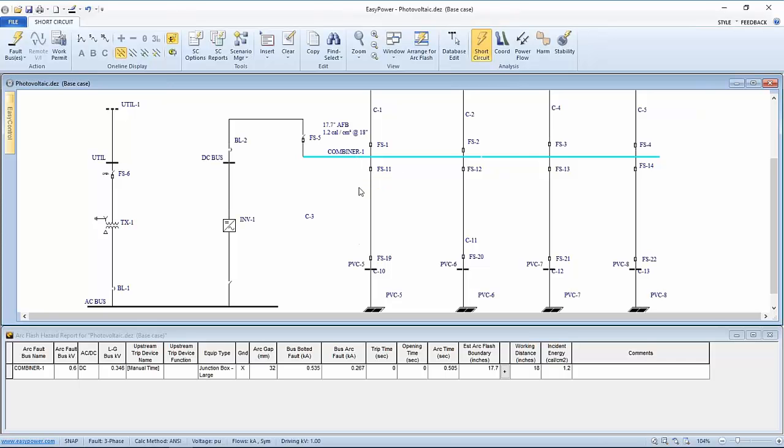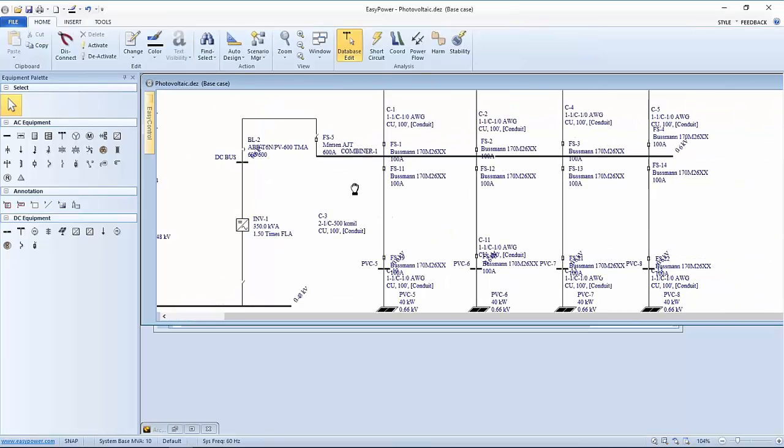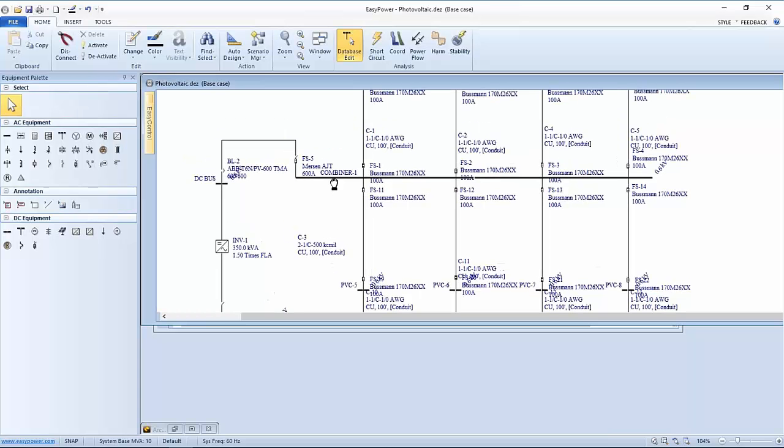I don't recommend that anyone be cavalier in these considerations, but when we're talking about a maximum of 200 amps and a voltage of, I think it was 600 volts, that is dangerous, but it's not an arc that will last 2 seconds. In fact, in my estimation, it would last considerably less than 1 second. Okay,